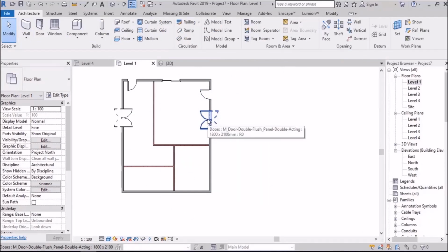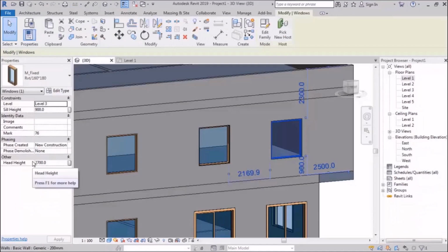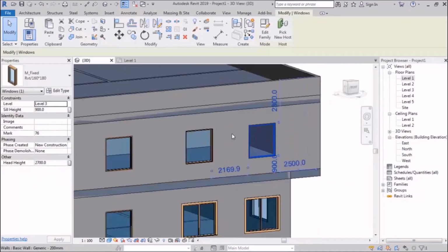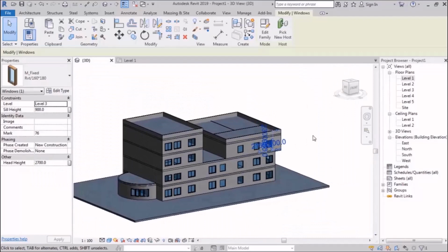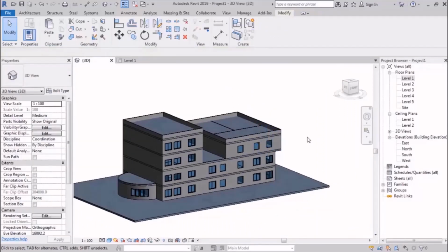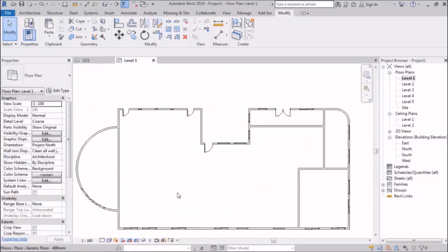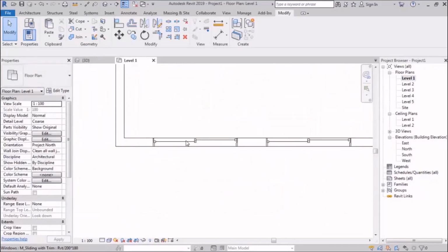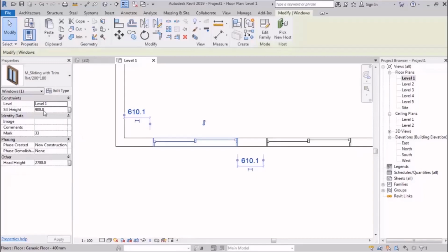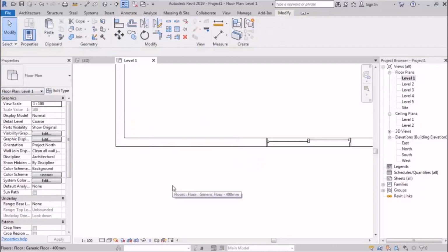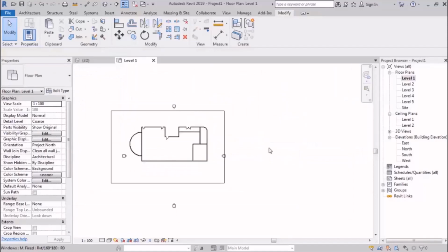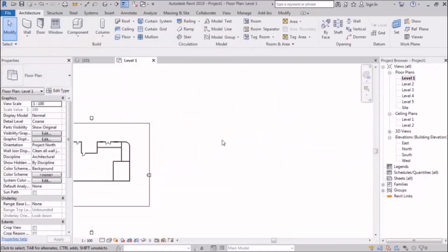Alright, I told you everything about how to place a window and a door, but there is something, and that's the height of a cut in the plan. When I go to the plan, you see this window, for example, the OKB is 90. Let me make it 1.10. Well, it's okay, let me make it 1.30, and it's gone. Now let's find out why this happened.